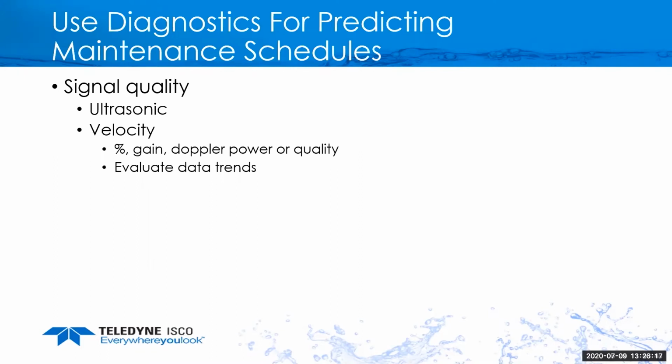And spectrum ratio is a reading that is telling you how many of the particles are coming at it. And what I mean by that is in a perfect world, your hydraulics, everything's coming straight at the sensor. That velocity spectrum ratio should be 100%. If it's not, that'll tell you that you have something going on in that channel. You've got swirling, you have a broken pipe, whatever. So a lot of things that you can use on a standard area velocity.